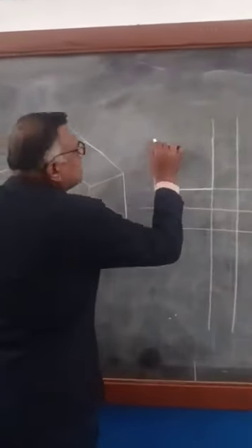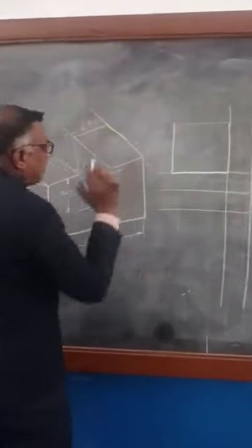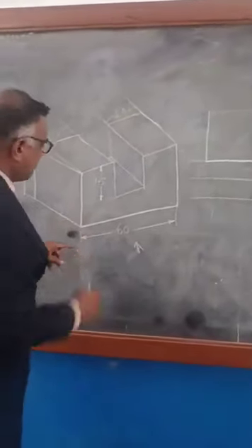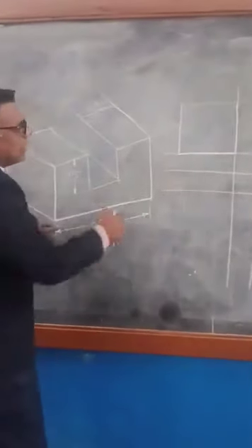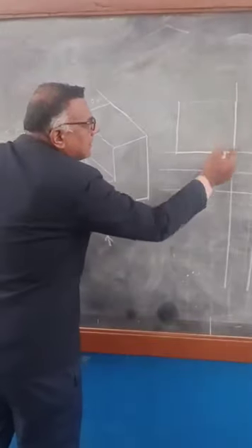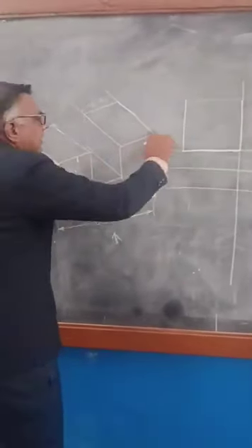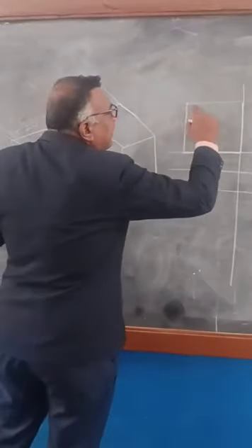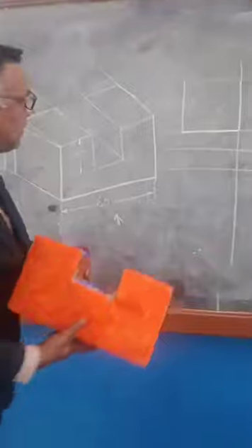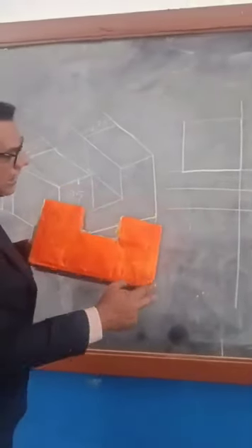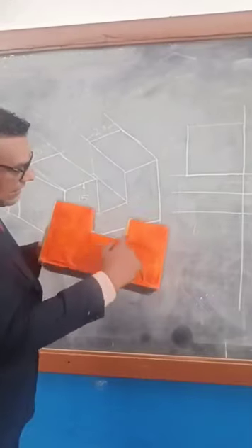So first construct a box on this. It is not an original object, I just make it to complete the box. So when you are drawing from this side, this inclined line of 30 degrees, I make it a horizontal line. This vertical line, I make it a vertical line, and this vertical line, I make it a vertical line. So this is the inclined line. I draw just a rough line for the horizontal line. Now, till now I completed this portion, and this portion, and this portion. So now there is a slot.